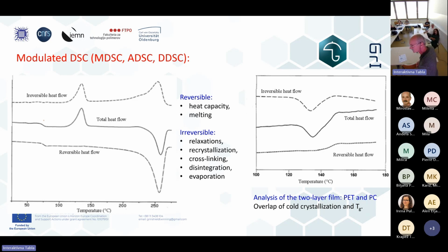However, it's hard to say. But if we use modulated DSC, we see nicely the glass transition and some cold crystallization that was here.